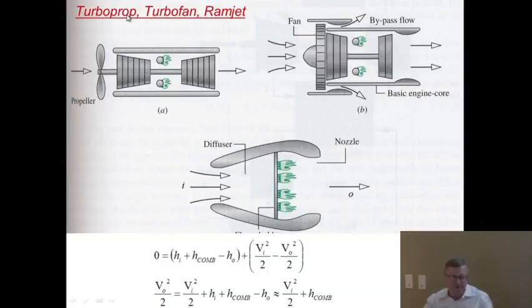Most airplanes, most commercial airplanes that we fly in fact, are some version of a turboprop, except the cowling goes around the propeller. And that then becomes a high bypass turbofan engine. In a high bypass, it's exactly the same thing, except you have the cowling here and here, which is as if you had a propeller with a housing around it.